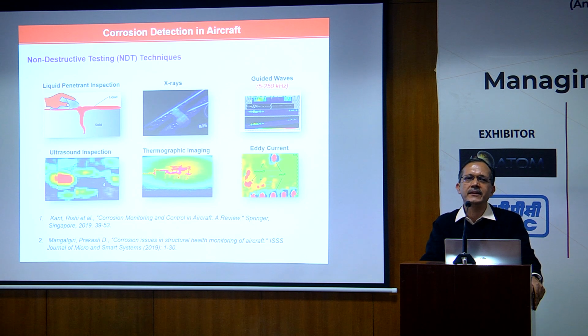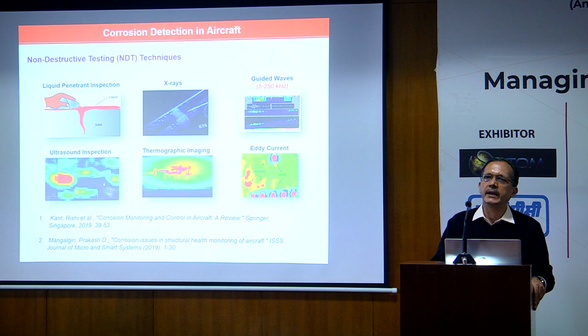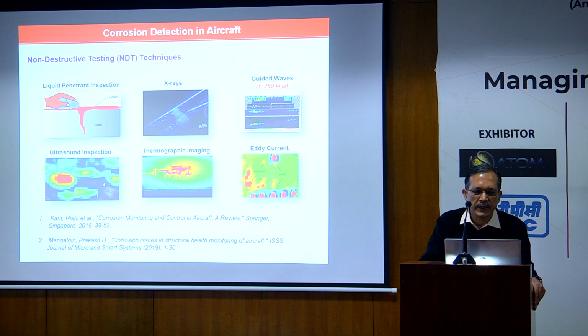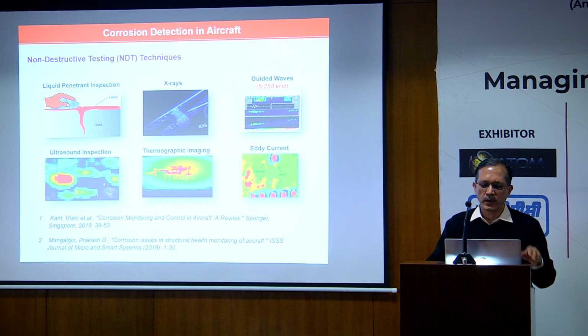The detection in the aircraft is basically done by non-destructive techniques. There are a large number of NDT techniques, some of which I have listed over here. Not all of them are listed because of the lack of time. We have liquid penetrant inspection, which is a very, very simple, facile technique, the X-ray or radiography, the guided wave technology, the ultrasound inspection and thermographic imaging, and of course the eddy current. I'll just take two simple examples.